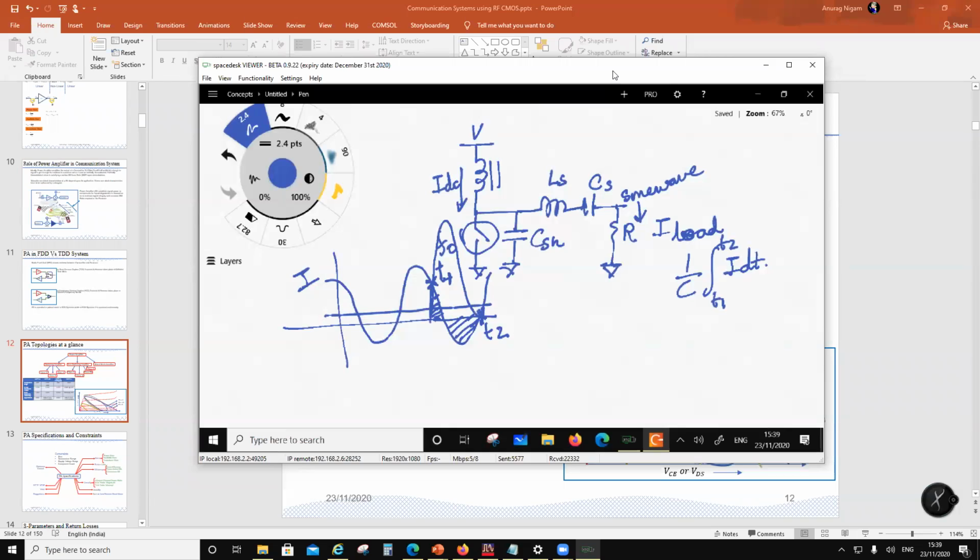But this piece of the sine wave which is shaded is moving through the capacitor, causing the voltage. So the voltage across the switch is maximum, but the current through the switch is 0. Most of the entire current, this shaded piece of sine wave, is going through the capacitor. When this happens, the net power dissipated in the switch is 0.